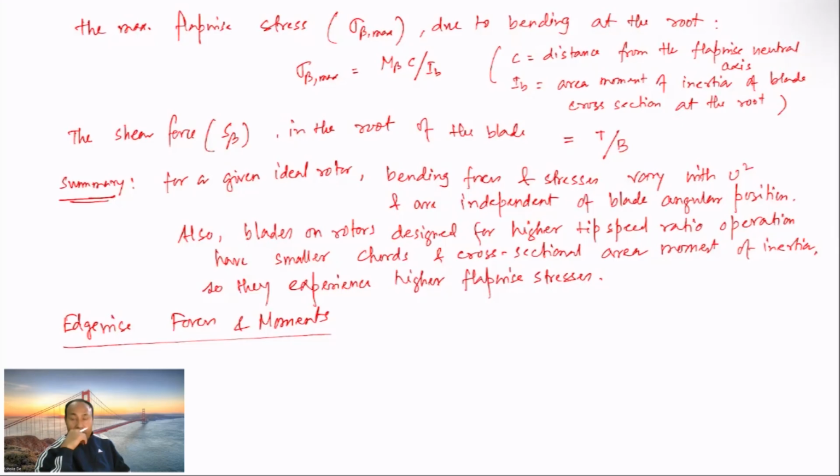But one thing one has to take into consideration is that during operation, it may possibly happen that these edgewise moments due to the blade's own weight can be significant and may have a significant impact on the overall forces or moments acting on the turbine.